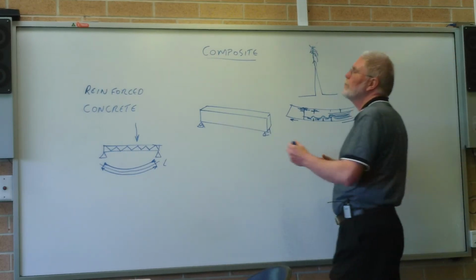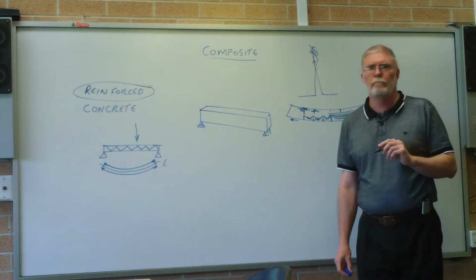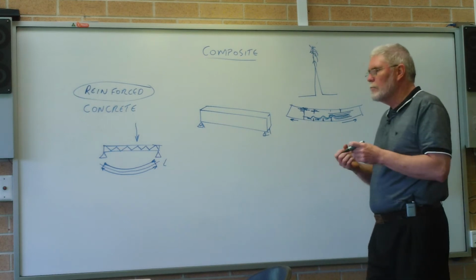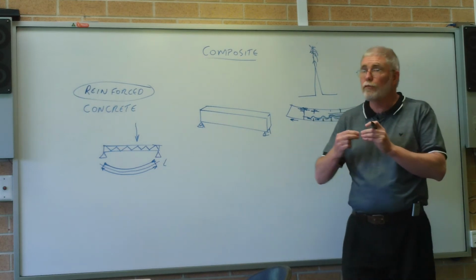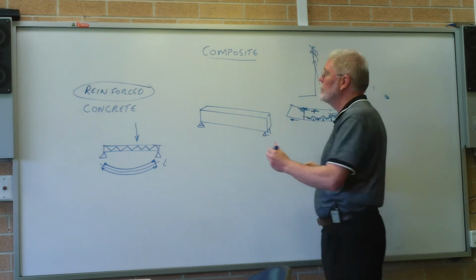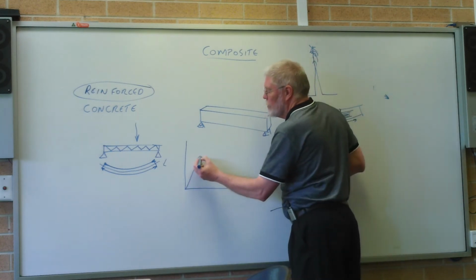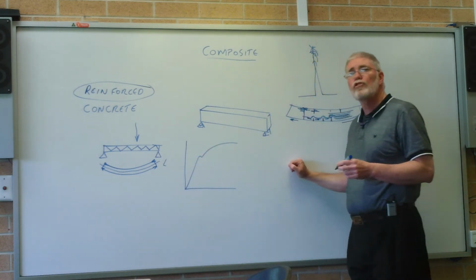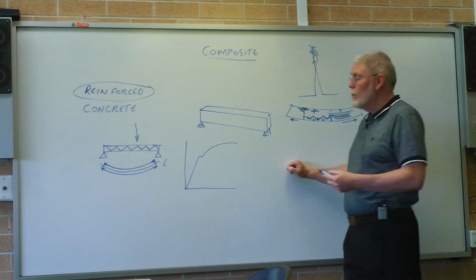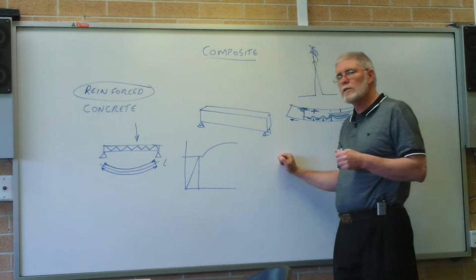This is where the reinforcement comes in. What's steel good at compared to this? Tension, good. Steel can be made to resist tension by deforming. Why does it have good tension capability? Go back to one of these diagrams that we've looked at. What's this one called? Load extension diagram or the stress strain diagram. Right? That gives me something about this range. What is that range?